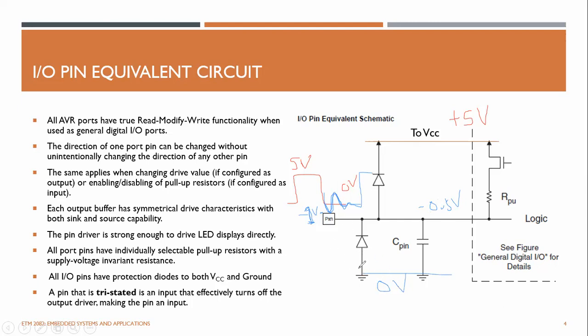You know, this diode can conduct because 0 is higher than -1. So the current can just pass through this diode, forward biasing it and allowing the current to flow through this diode, right? So it's similar to the previous case, we can consider this voltage drop as 0.3, a typical Schottky diode voltage drop. So in that case, this voltage might be minus 0.3.